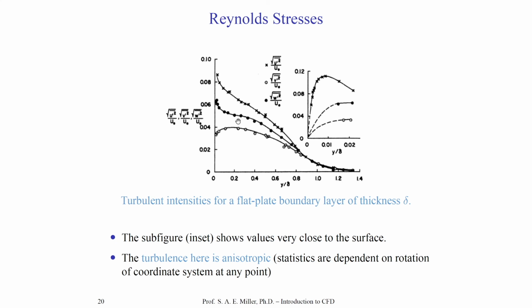You can see this is impossible in this particular case, so we call this turbulence anisotropic. Therefore, we have to be very careful when applying the ideas of Kolmogorov to, say, a turbulent boundary layer flow or any type of flow where there's inhomogeneities or anisotropy. Thankfully, turbulence itself generally returns to isotropic regime over time as a so-called memory. This is a beautiful theory in itself.